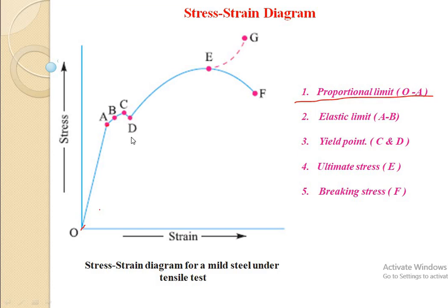As we have already defined, stress is actually the resistance offered by the material to the applied load. So if due to the application of load there is an elongation of the material and these particles move away from each other, there is only a slight resistance from the particles, hence there is a decrement in the stress value. Look at this, there is a decrement in the stress value at point D. This is known as the lower yield point. Now at point D, the specimen regains some strength, and higher values of stress are required for higher strain.